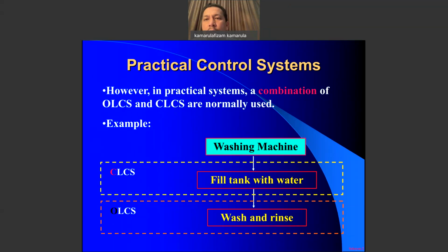So you have sensors that read the water level as an input. This input goes to a control block, a process that compares the water level with the desired one. Then the output is the current level. Once the output of the current water level is fed back, the system makes a comparison, just in case the current water level has already reached the maximum. So the feedback keeps on going until the tank is full.